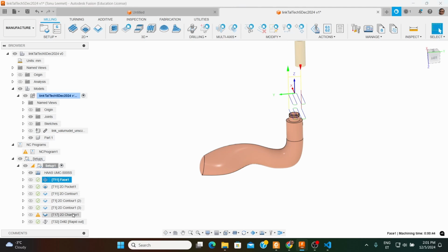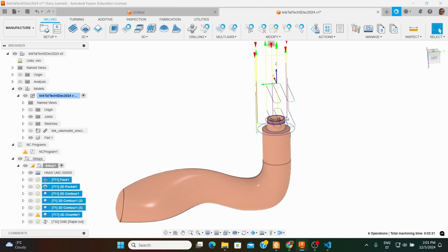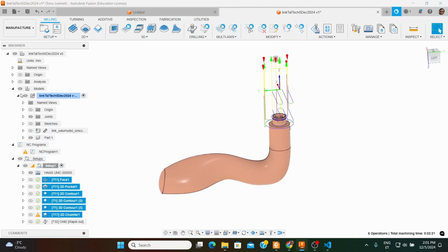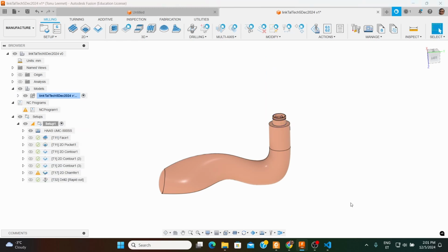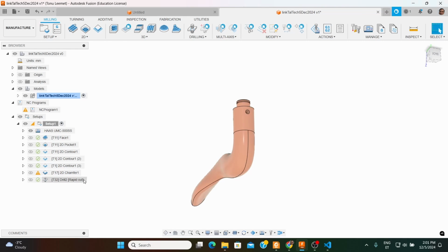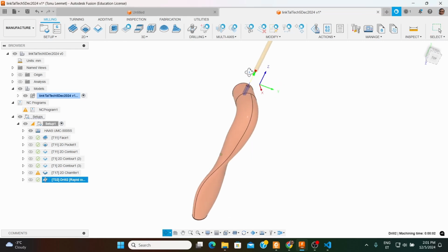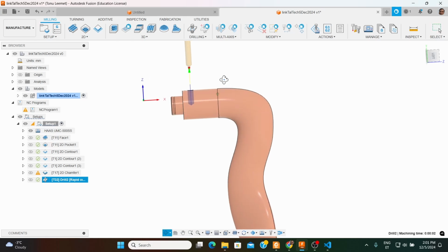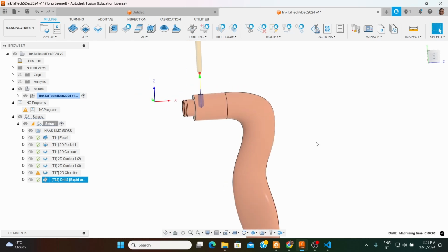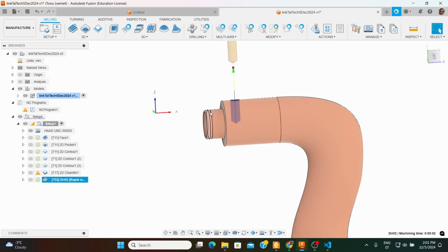These toolpaths will take care of the part, and then the multi-axis fixture, multi-axis indexing, when it comes to play, is only for this drilling. And you see what we did, we just kind of rotated our work coordinate system for that particular operation.